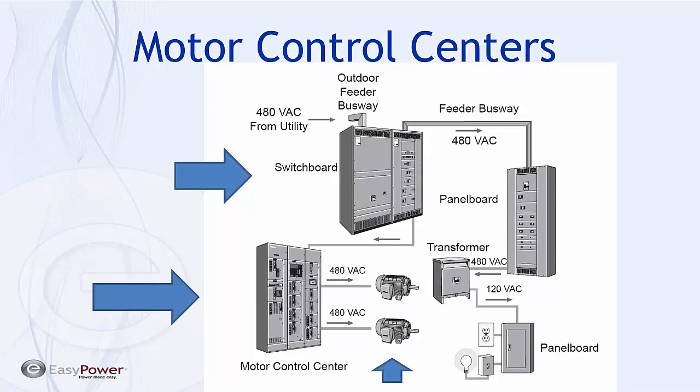To properly protect these devices, the coordination module must display performance curves for these elements wherever they reside in the system. So we want to identify fault currents, both arcing and bolted fault currents in the TCC plots, and see which protective devices is activated for any of these types of loads.